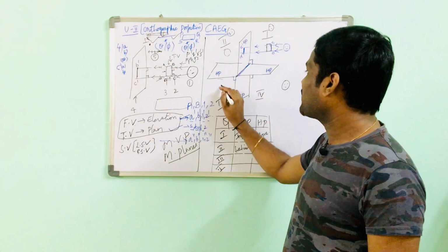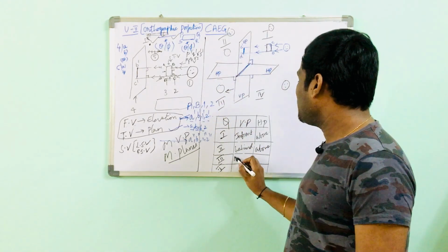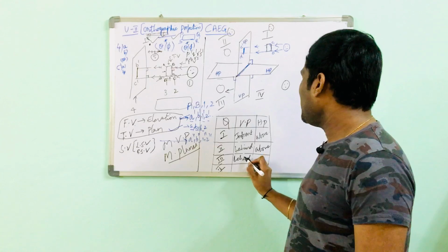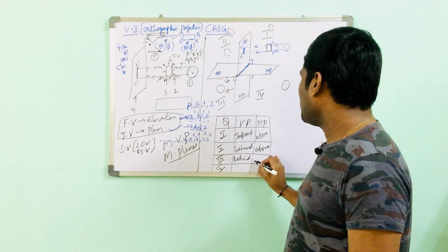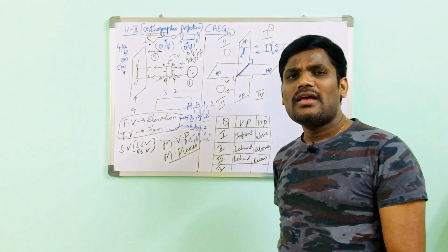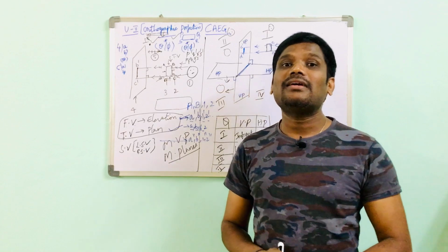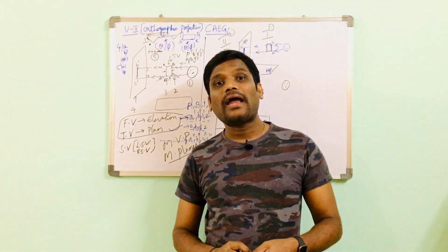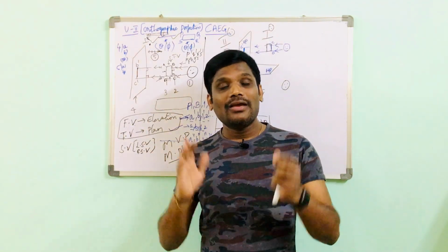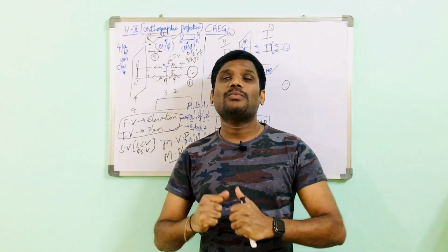Later, the third quadrant is here, where it is again behind the vertical plane, and there it is below the horizontal plane, dear students, below the horizontal plane. If a question of 1 mark is asked like this, the point P is 30 below the horizontal plane and 20 behind the vertical plane, you should remember that 30 below and 20 behind. It belongs to which quadrant?